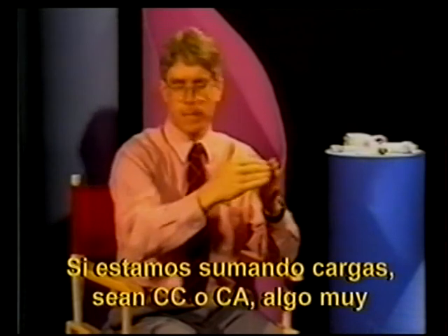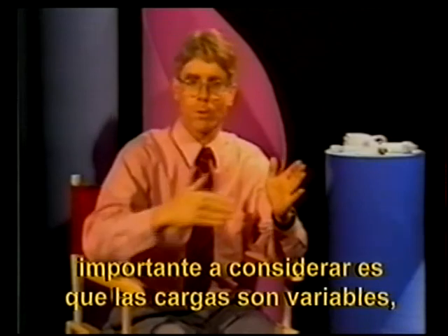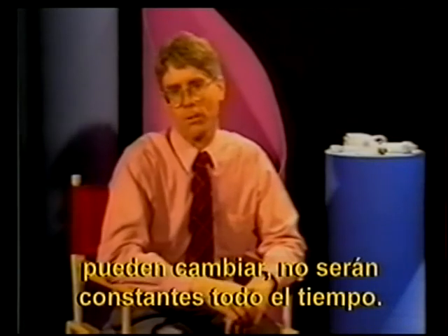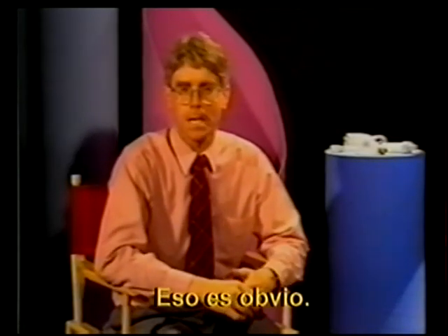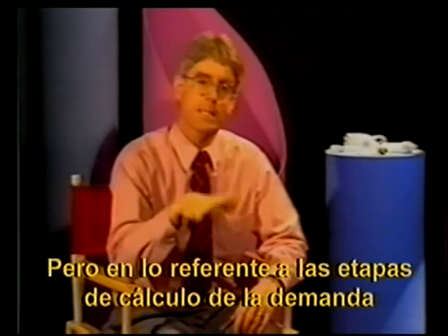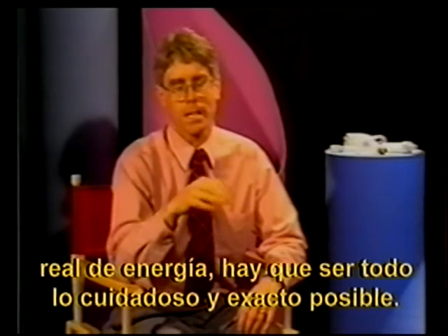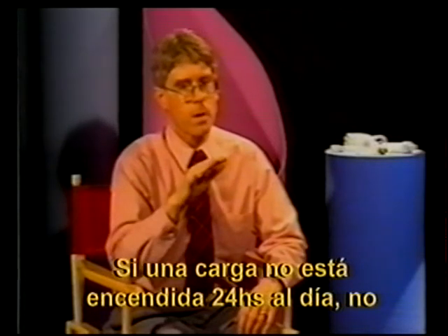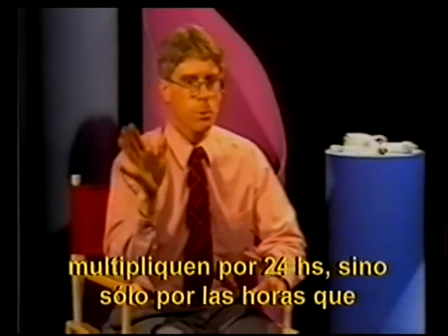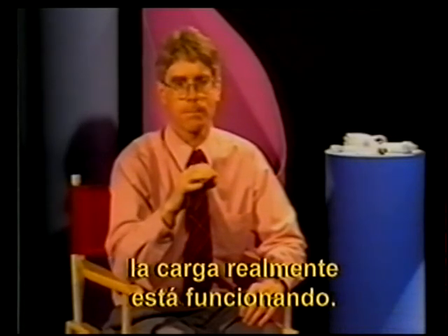If we're adding up loads, either DC or AC, a real important thing to consider is that loads are variable. They might be changing. They won't be constant all the time. That seems pretty obvious. But in terms of our calculation steps, you want to be as careful as you can be. You want to be as accurate as you can be about the actual energy demand. If a load isn't on 24 hours a day, don't multiply by 24 hours. Multiply only by the hours that it's actually operating.